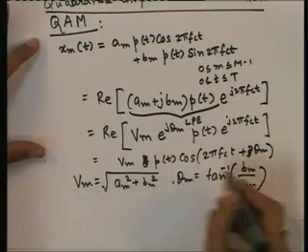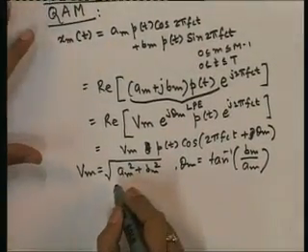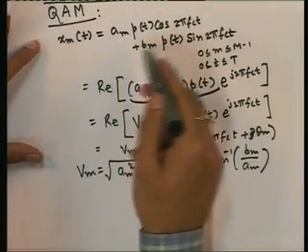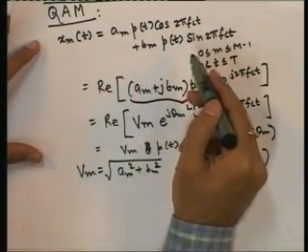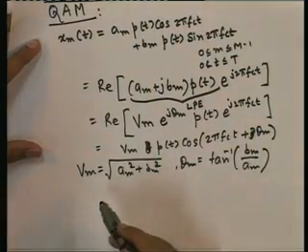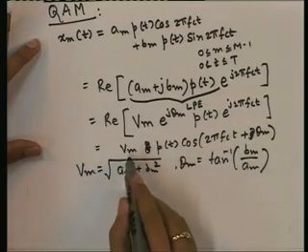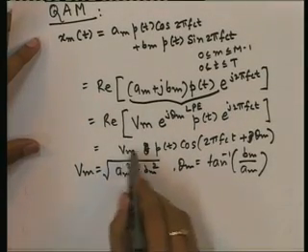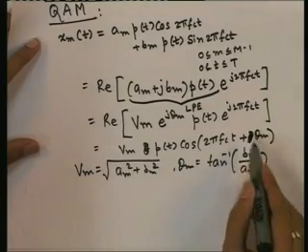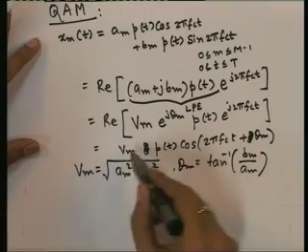So this can also be said to be a joint or combined amplitude and phase modulation. In the Cartesian view we can say that it is a joint amplitude modulation scheme, modulating two carriers, whereas in the polar coordinate system we can say that it is modulating the magnitude as well as the phase. In PSK modulation, it was only phase modulation, V_m was constant.